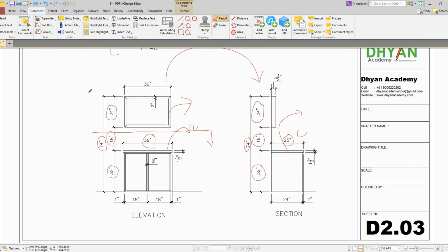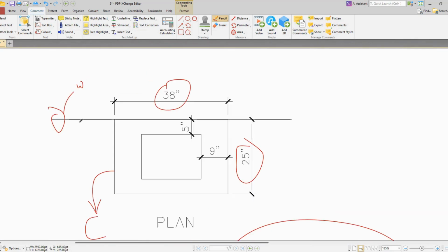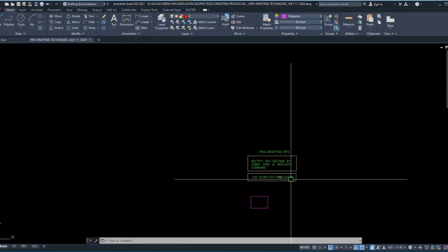So what I suggest is, wherever your countertop is, try to develop your view until that height only. Especially in interior room conditions, we do that. For other views, we can always create horizontal sections or vertical sections. For sectional information, we'll discuss that in different classes, not right now. Let's first focus on the actual views. So right now I'll start with the plan view.